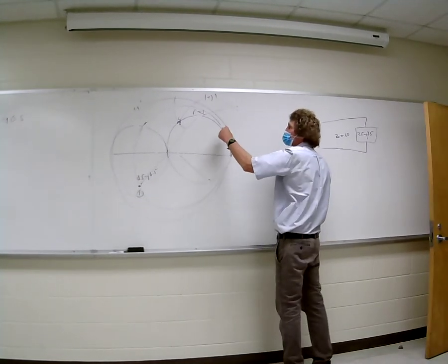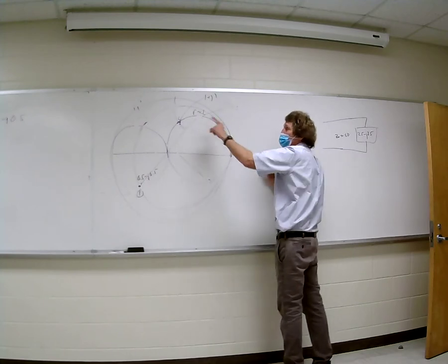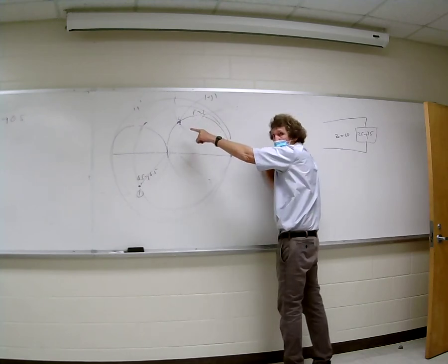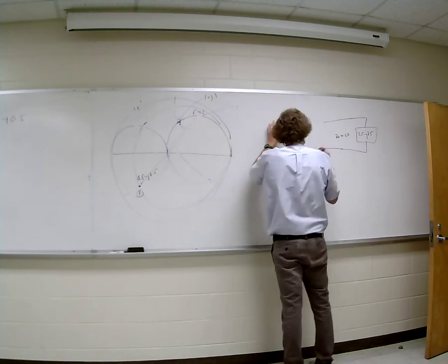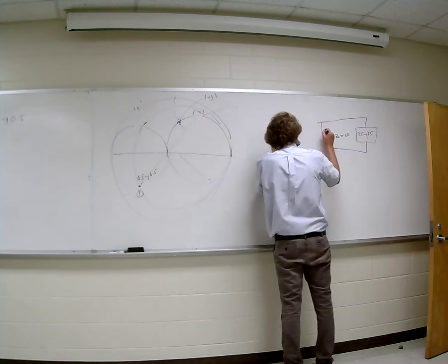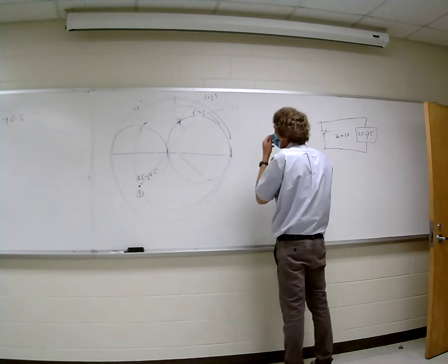Well, maybe it is. Let's see, we want to get rid of this J1, so this is the admittance domain, correct, class? If we add a capacitor, we'd be adding positive J, right? We would actually want to add an inductor. Y'all follow me? But it would be in parallel. This is not a good design. So this would be some inductor, but we've got to figure out the value.